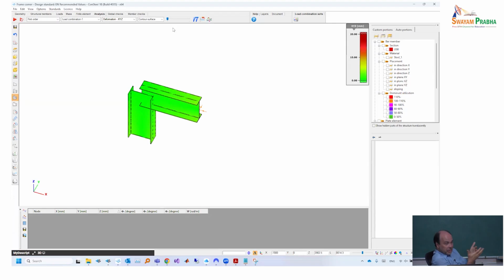But without thinking too much, we can also transfer the bi-moments like this. Mathematically it's possible, although in case of the bi-moment, it is probably even more important to know how the real connection really looks like, because everything depends on that. But we can do something without saying what it is.